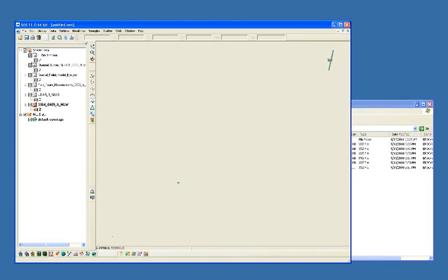Now you can turn some of these on or off, but we can see that the data that we have, there's one little piece down here in the lower left, there's one here, and up in the upper right. We can see that there's 3 different coordinate systems, 3 different types of datum horizontal corrections that we're going to have to make here. If we zoom, and this is the zoom tool, we can draw a box around this one here and zoom in.